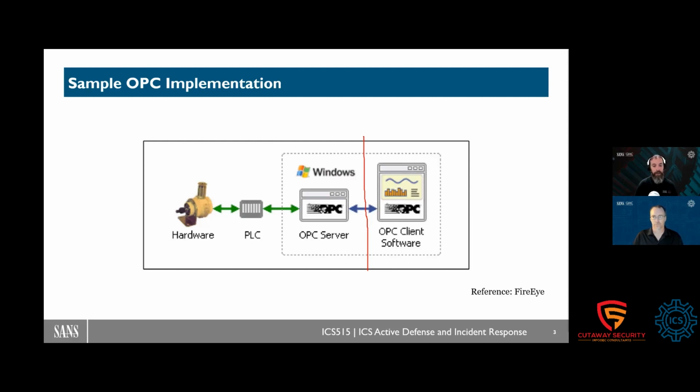We did a red team exercise recently where it was looking at an OPC client. The server was sitting in the IT DMZ and polling using OPC AE from our OT environment with a few different controls around that, but it was only using OPC AE for alarm events because that was part of their alarm events management system.